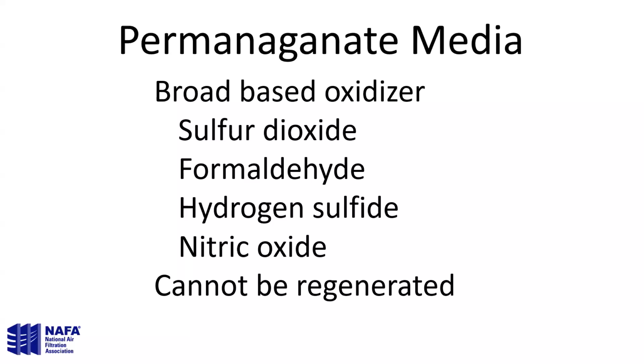One of the major differences between the activated carbon media and the permanganate media is activated carbon can be regenerated. And we do live in a world where we try to recycle. So when you can use activated carbon, it's good because most of the time, if you have enough of it, it can be recycled. If you use a blended media, it can't be, it has to be disposed of. If you can separate the two because you need both, it's always to your advantage.